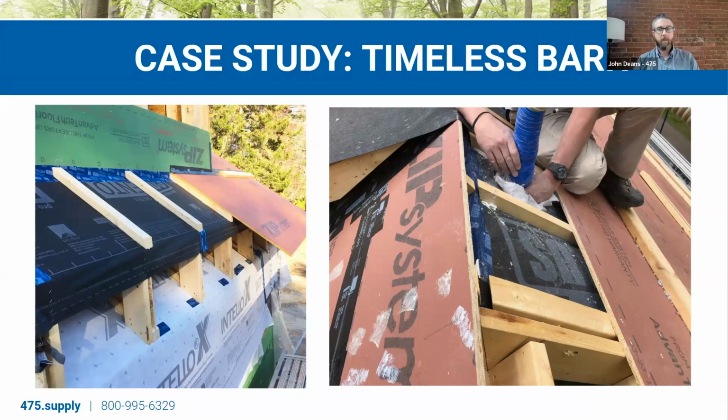The other thing that we did that was really helpful is, we were able to sheathe this whole thing, but this top layer where they're doing the dense packing, we just made sure to screw down so that we could back out those screws, take that piece off, they could do their dense packing, we could put it back down. And in the meantime, we had a fully sheathed roof. We also did this with the middle section of sheathing on the roof. We nailed off the first layer, and then the second layer, we just screwed in enough to keep the sheathing on and be able to continue. Then we nailed off the next run.